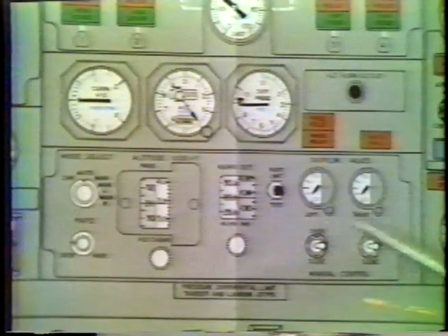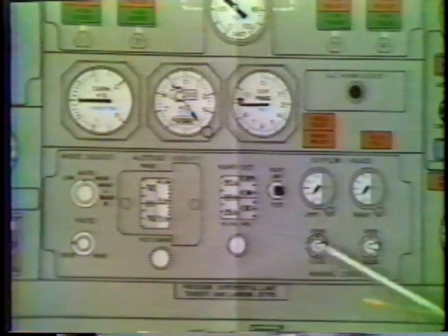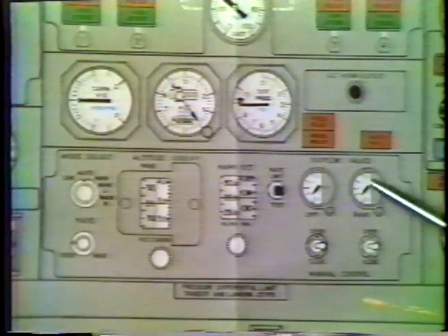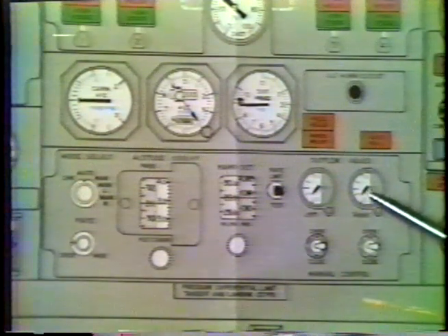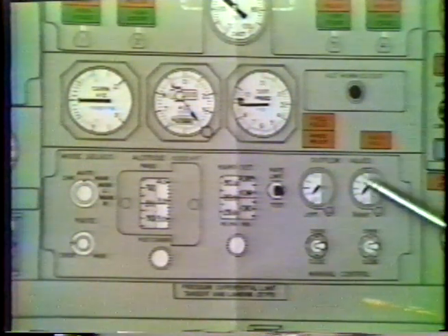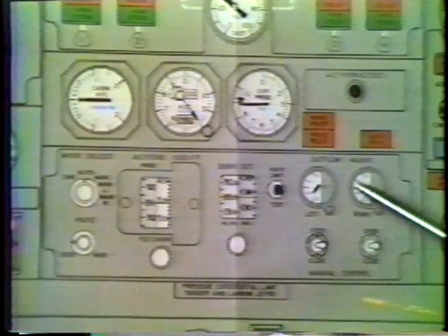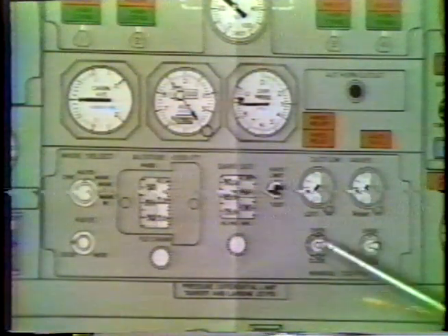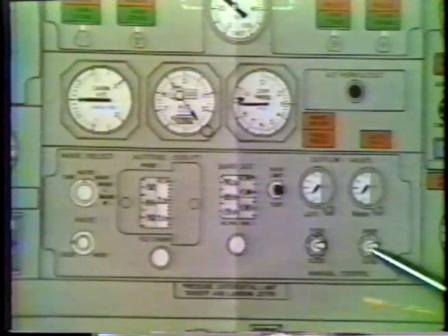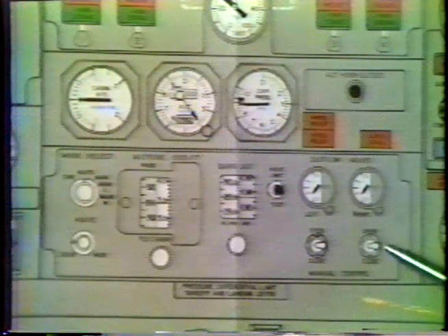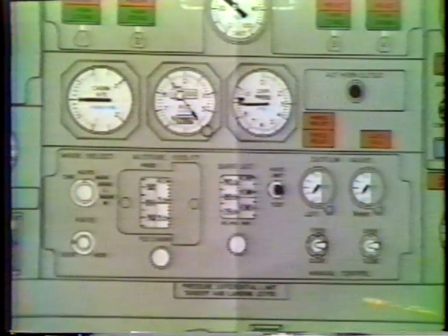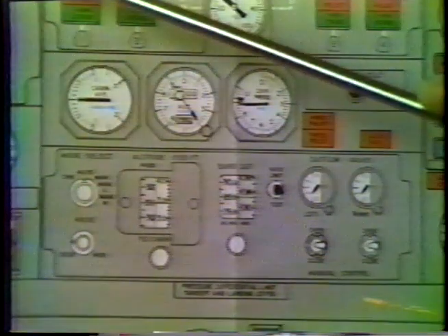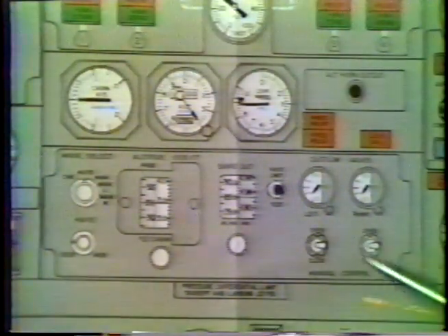One thing I'd like to point out here is in auto, the outflow valves are operated by AC motors, which is somewhat quicker than manual. When you go to manual, the outflow valves are operated with the toggle switches, which receive power from the aircraft battery. And of course, anytime you're in an aircraft, the battery switch is on, so the outflow valves should be operable.